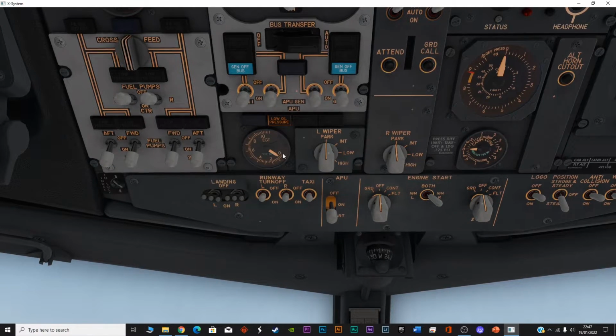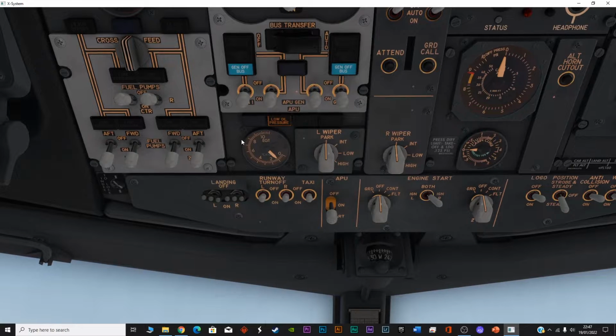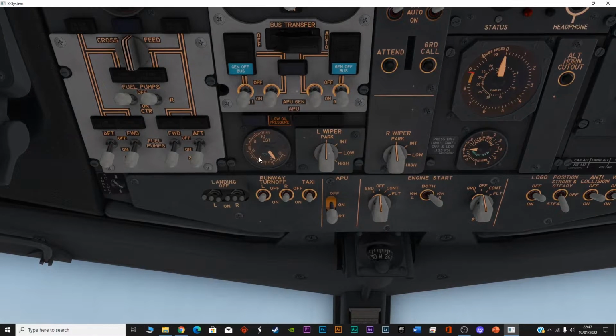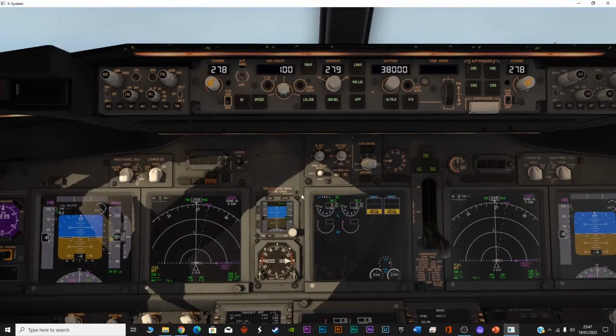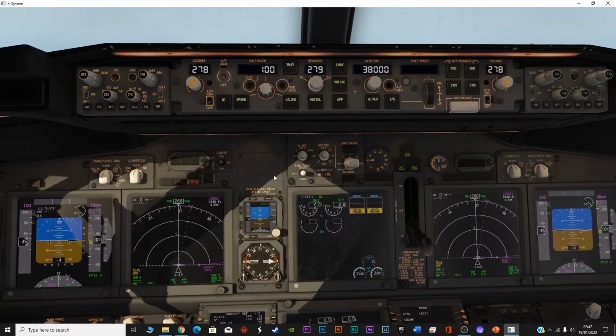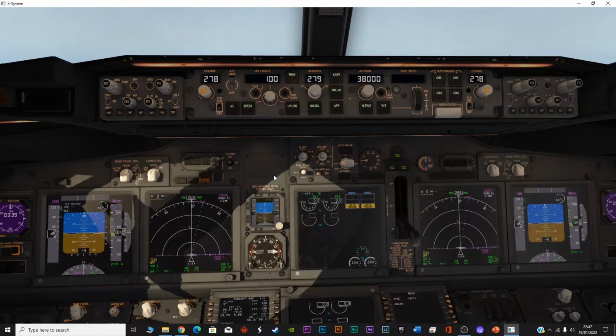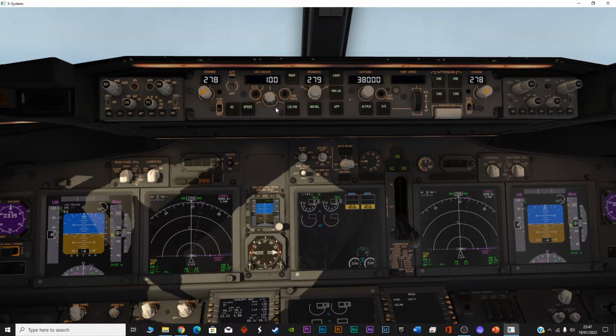Right now, within some time, you will see this gauge moving. It will go to maximum, and then it will stabilize at some point higher than 4, and this light will go bright. So then it will be time to switch to APU generators. But right now, I will wait for it. So before doing anything else, I will go to this panel, EFIS, that is Electronic Flight Instrument System, which is over here, and I will configure some basic settings.